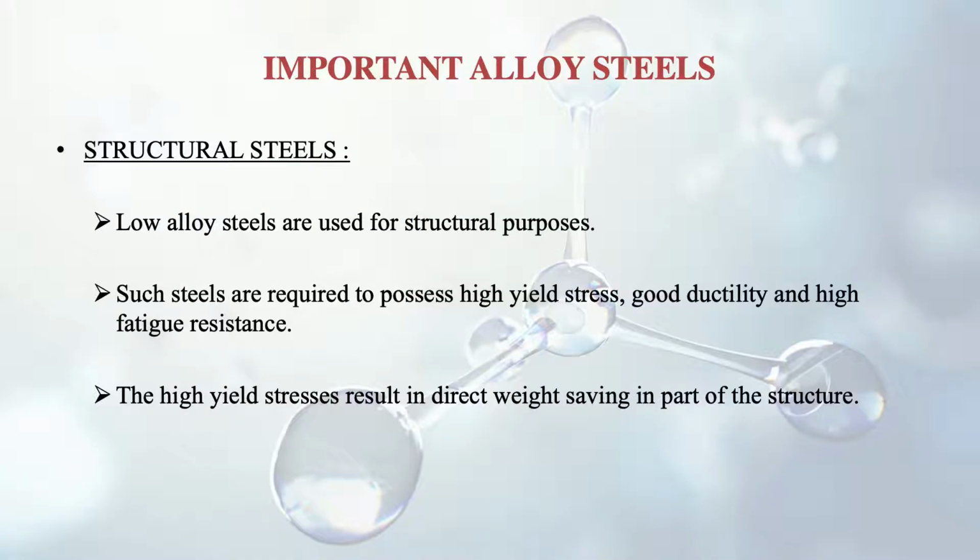Ductility is very important, and also fatigue resistance is very important, because there are different kinds of loads which these structures have to bear, like wind loading and all those, so we need to have high fatigue resistance. Then the high yield stresses will result in direct weight saving also in part of the structure.